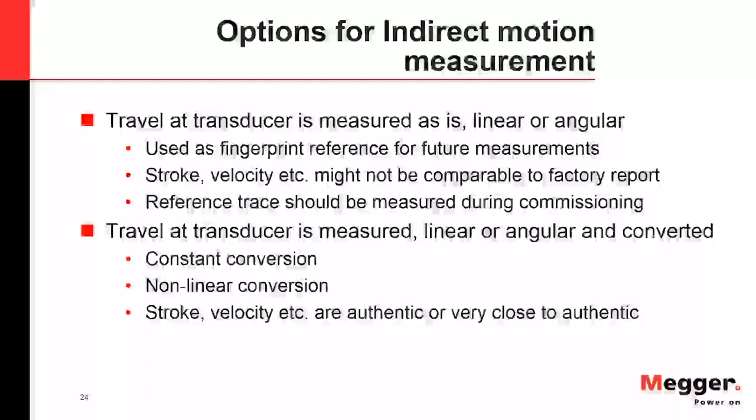So you go through, all right, this is what we got. Preferably you're doing this during your commissioning test so you know that circuit breaker is in good condition. And then from every test after that, you compare to that original one, see is our stroke varying, our velocities, is any of that stuff changing, overtravel, whatever.